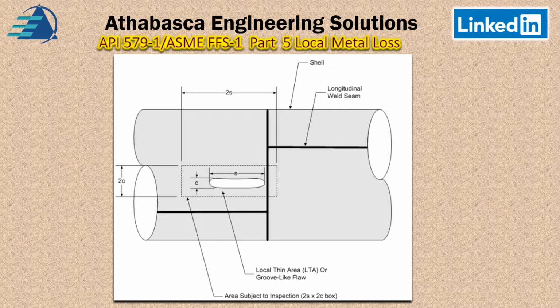And so with the local, whether it's an LTA or groove, we have to identify our subject area of inspection. So this is guidance. When we do our inspections of this groove, we need to be over and above that, if practical, of course, to get the full thing, to make sure that there's nothing else there. So this is what API asks for.